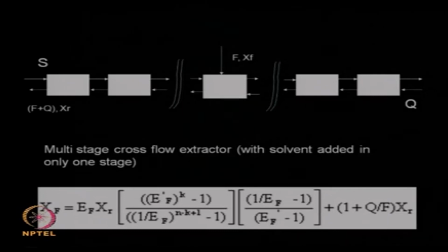So again although this equation looks very difficult or complicated, it is all based on mass balance. There is no reaction taking place in extraction, you just have mass balances happening. You have mass balance for input, mass output, and then you just equate the input equal to output, and that gives you a balance for one stage and so on. So you build up the multi stage process.